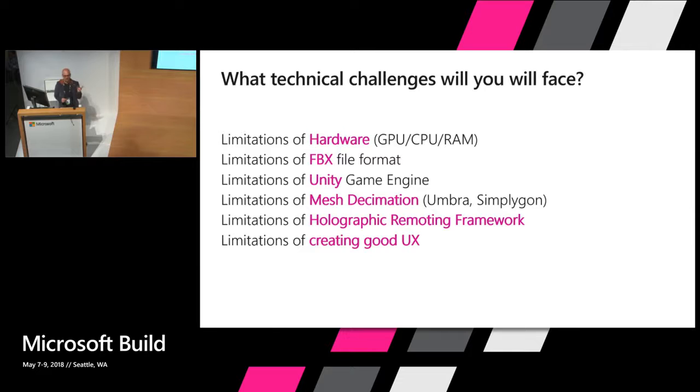So what are the kind of constraints you're going to find? The next question is, if you want to load a massive model, a large 4D construction simulation, not just a one or two day look ahead into the future, what do you have to deal with? The limitations you're going to hit: you're going to find that there are hardware limitations right off the bat with how much you can load onto the HoloLens. The FBX file format, which is a common data exchange, we found also has limitations, which I'll talk about.